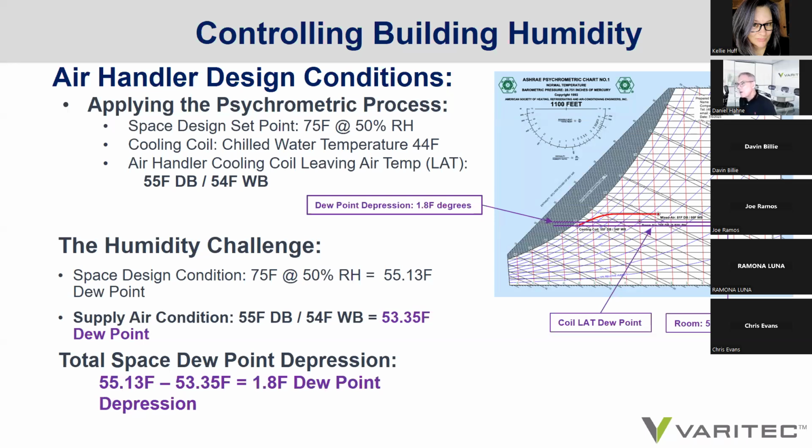But as buildings are becoming more and more energy efficient, our airflow requirements to meet our peak sensible design days are going down. Our airflow rates are going down, but humidity is not going down. And I really have to thank this education and awareness due to Munters that has some great information on dew point control. So anyway, that is the growing challenge.